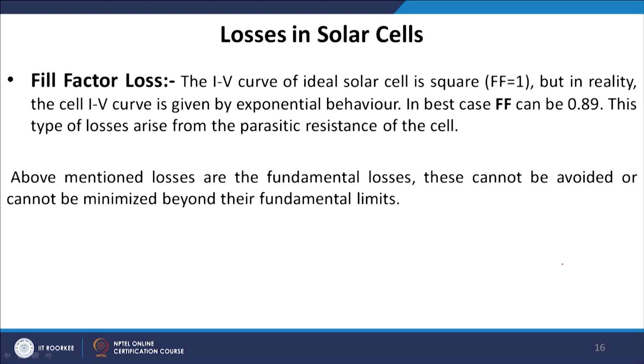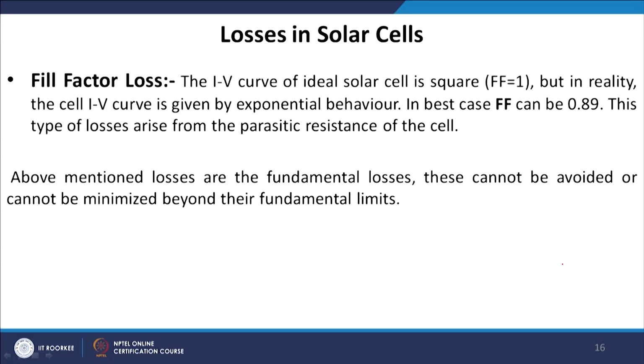As I said, if I have a higher value of the series resistance and a lower value of the shunt resistance, then the fill factor changes. Looking at the fill factor we can say how good the device is, because if the fill factor is very high, close to 1, then we have a higher efficiency. So the above mentioned losses are the fundamental losses. These cannot be avoided or minimized beyond their fundamental limits.